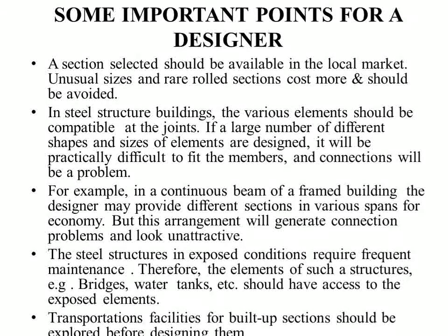This is the only difficulty here, that we require frequent maintenance, that is coloring, oiling of the steel members which are exposed to the air, to the water, etc. Therefore, the elements of such structure should be protected from the water, from the air. The next one, the transportation facility for built up sections should be explored before designing them.